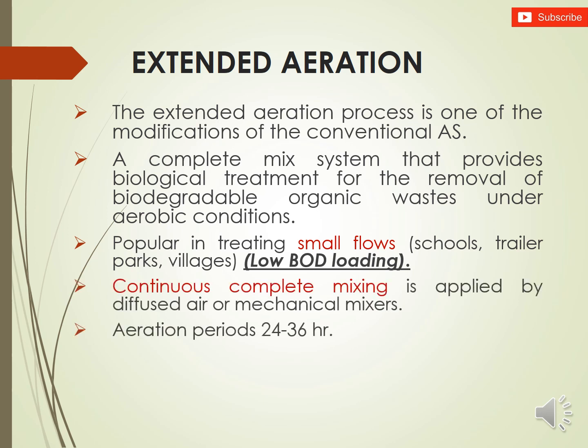And the continuous complete mixing is applied by diffused air or mechanical mixers, and the aeration period is longer than the conventional activated sludge. Okay, 24 to 36 hours.